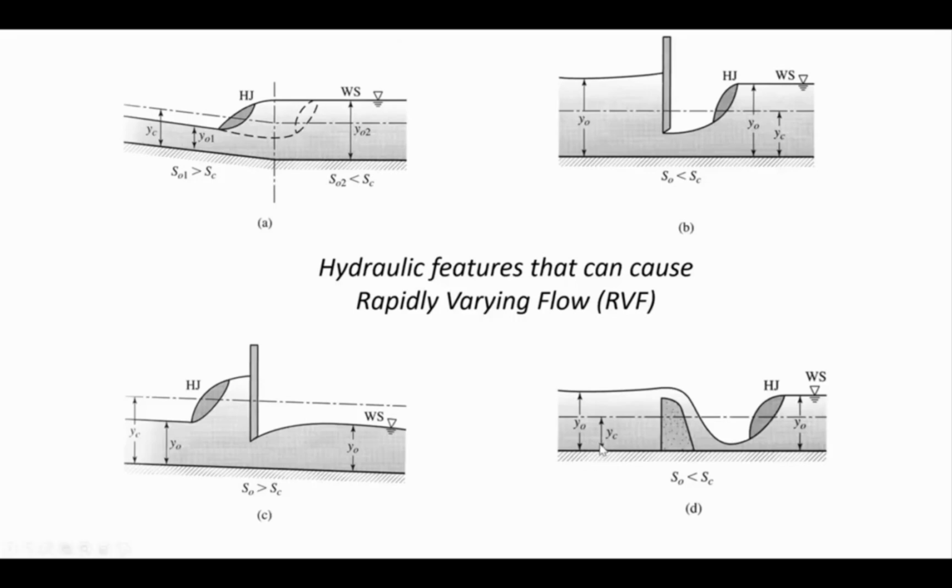And rivers are just made out of rock and gravel and soil, and if you have water that's moving very fast, it can sweep away sediment, and it can dig through the channel and move things downstream that you'd rather have stay in place. It could erode the footing of the dam if we're not careful about that. So dissipating energy after a spillway is an important part of managing hydraulic jumps.